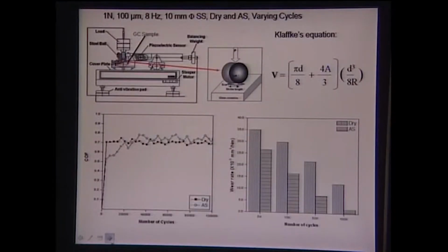Well, we have done some tribological testing on this M2 glass ceramic, and what we see here is that after testing against steel based materials, in dry conditions and in artificial saliva, you have this COF response, and we do not see any difference in this COF. So, in both the dry as well as SBF condition, COF is roughly 0.7.